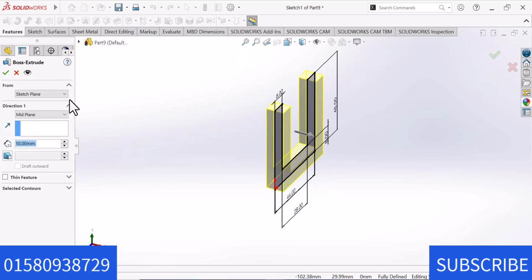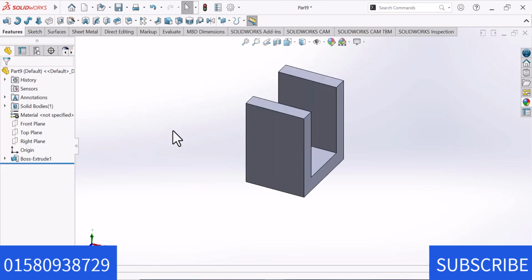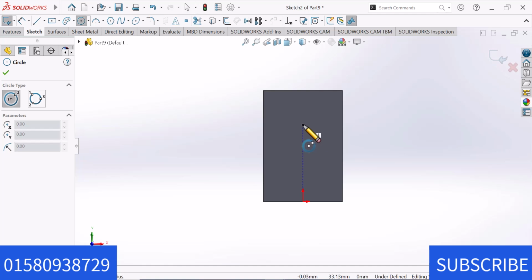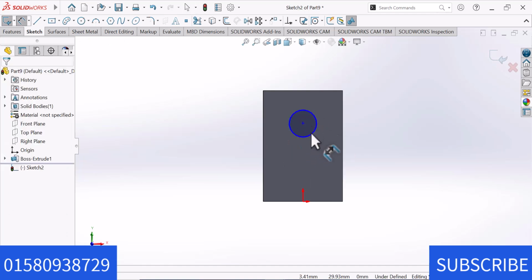Now go to Feature and select Extrude. Extrude from mid plane 34. Okay. Now go to this face and sketch. Now draw the circle here. Now give the circle below 24.